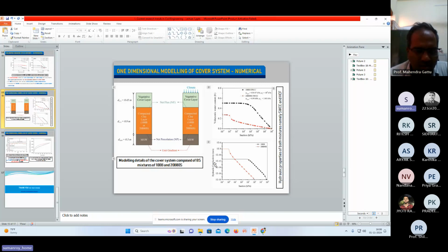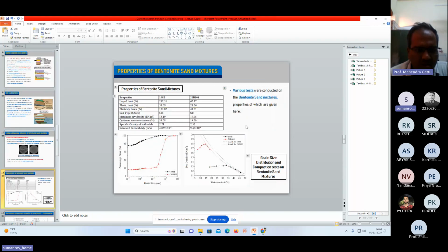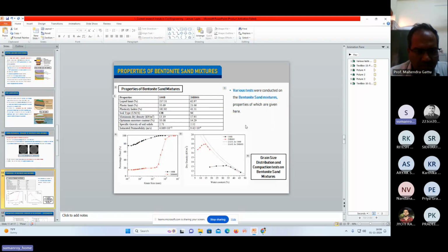Porosity and all these things are already given, sir. These are already given when you are giving the compacted clay layer: the porosity, void ratio, specific gravity. In this slide, parameters like maximum dry density, optimum moisture content are all already provided. So you have to input all these parameters, and it will calculate accordingly, the three-phase system, whatever is there.